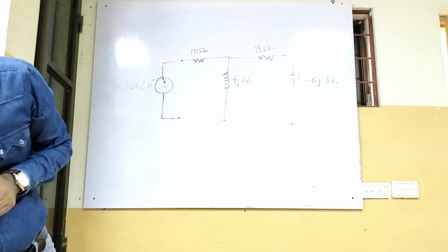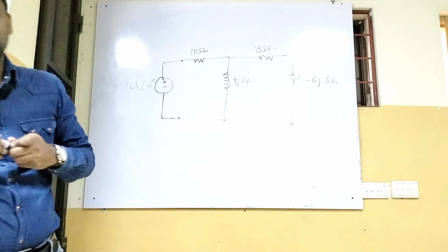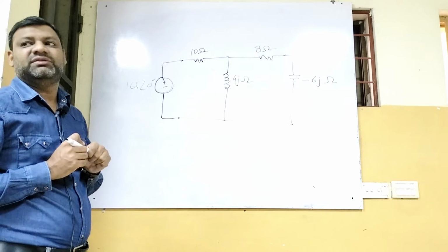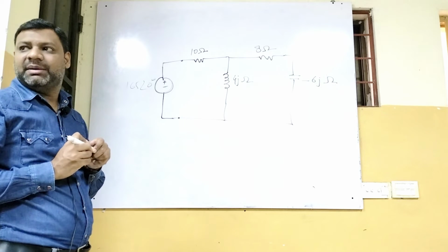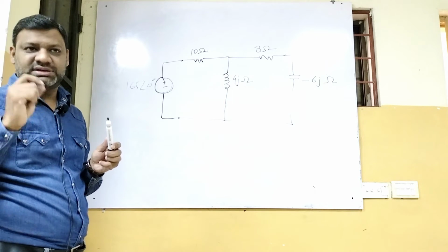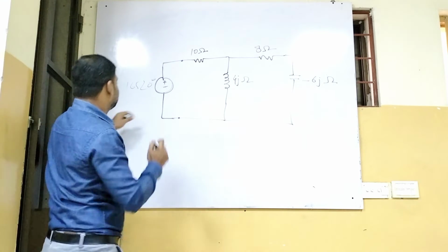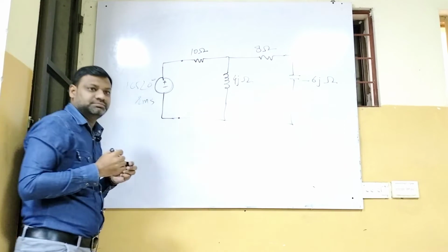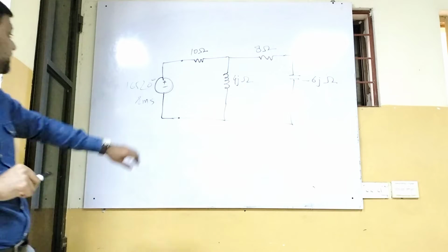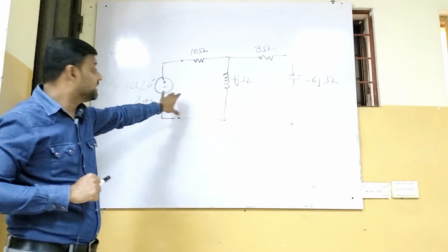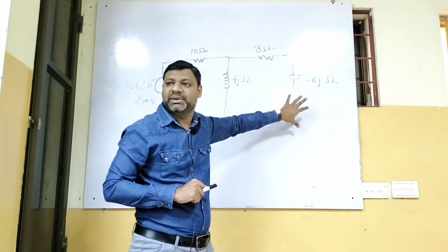What is the average power supplied by the source? We have to find out the average power as well. What was the formula for average power? Half of VM IM, or V RMS I RMS. It's given in the question that the supplied voltage is root mean square. So the values we find, the current or voltage across any component, will automatically be root mean square.